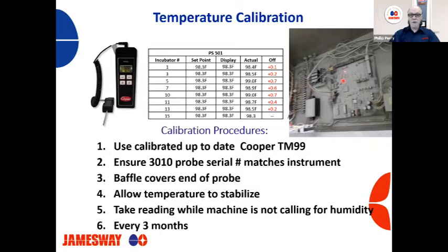And this can affect not only the operation of the machine, but also short circuit that board and just get some bad behavior from the machine. So I think every 3 months you should take an air hose, open that top box and spray that dust out of there so it doesn't affect the operation of your machine.